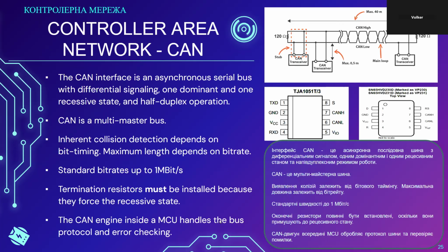So if you have a slow bit rate, if you decide that your CAN bus doesn't need 1 megabit per second, your CAN bus could work at, let's say, 10 kilobits per second. Instead of having a maximum length of, let's say, 20 meters, you can have a maximum length of 2 kilometers. So if the designer was in a position where the CAN speed can be dropped, that means that the CAN bus itself can be a very, very long bus, similar to RS-485, in physical length.